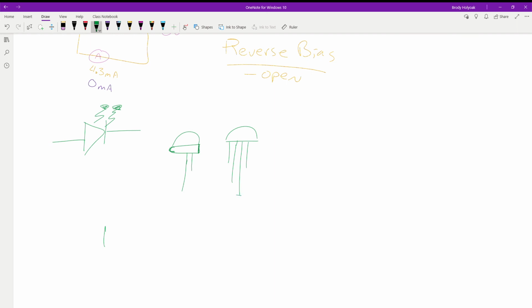This is your ground, and then you've got a red, blue, and green. What these do is they don't necessarily take a voltage like the 2.2 or what we're taking. They take a range. Their full range is digitally 0 to 255. If you were to break this up, you'd have 0 to 5 volts, and your voltage at this point is going to change based on that level. So you have 255 levels that your voltage can be at, and whatever level it is, that's how bright it's going to turn on that individual color.